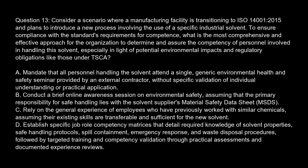Option C. Rely on the general experience of employees who have previously worked with similar chemicals, assuming their existing skills are transferable and sufficient for the new solvent. Option D. Establish specific job role competency matrices that detail required knowledge of solvent properties, safe handling protocols, spill containment, emergency response, and waste disposal procedures, followed by targeted training and competency validation through practical assessments and documented experience reviews.